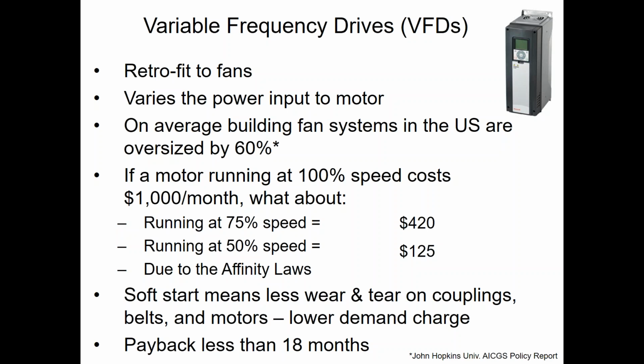That's interesting. You actually had a job where the fans were undersized. There's probably a whole story there about how that evolved. Maybe they expanded onto the system, or maybe the ductwork was too small and the fan can move the right amount of CFM, but it couldn't do the static. There's got to be some kind of story there.